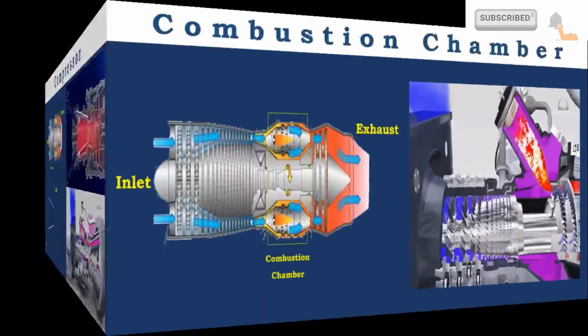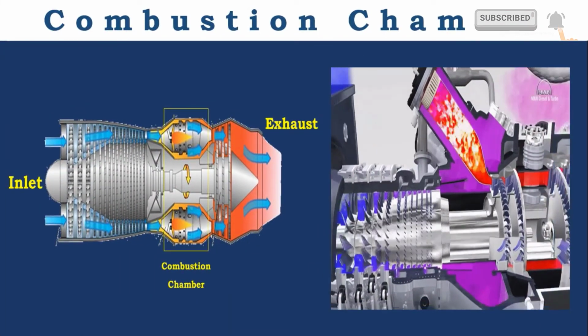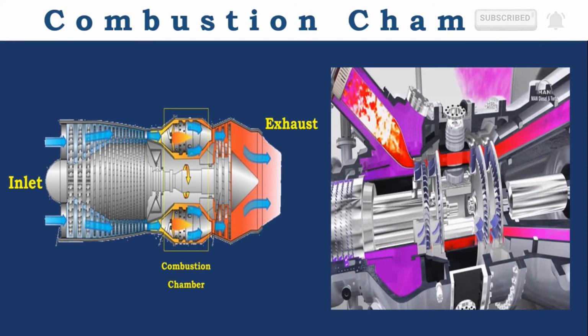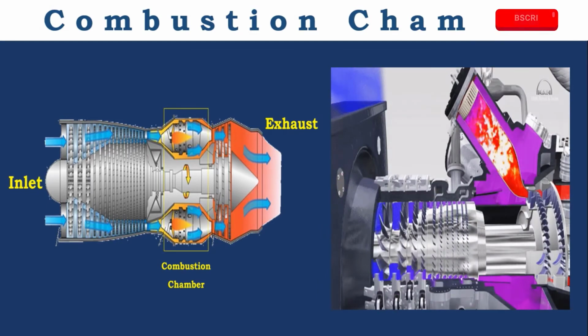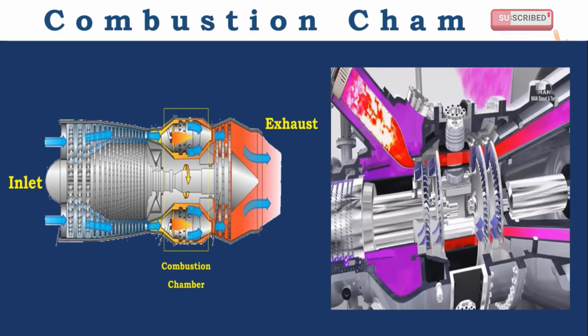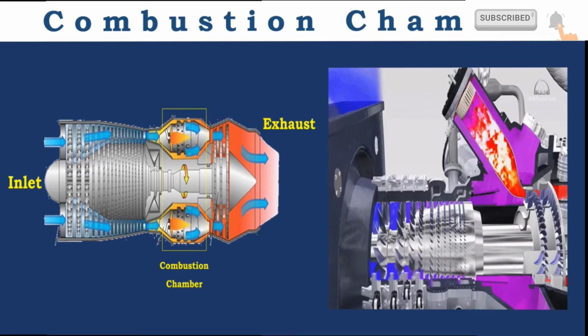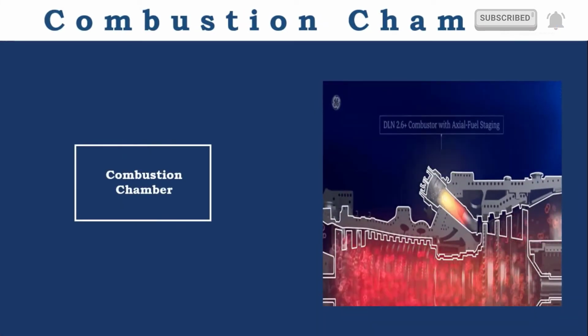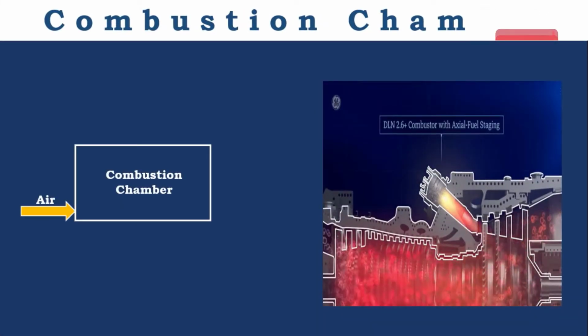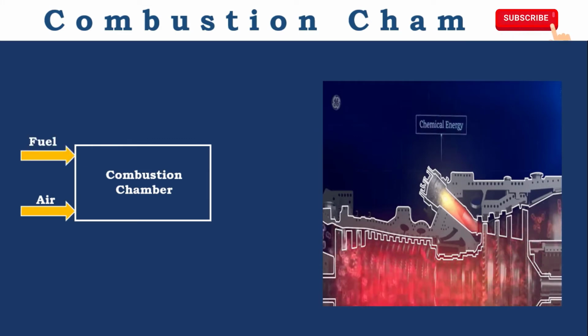Next, combustion chamber. The combustion chamber is also known as the burner or flame holder. The outlet of the compressor is connected to the inlet of the combustion chamber, so high pressure, high temperature air enters the combustion chamber where fuel is added to it.